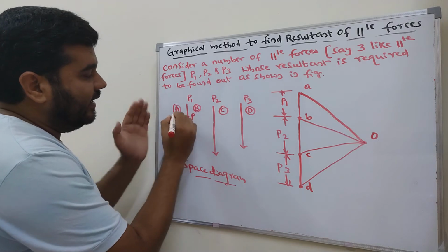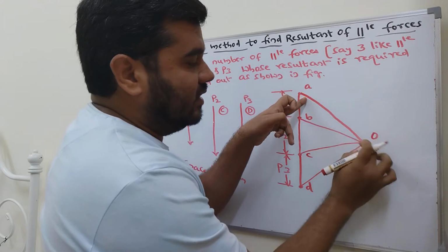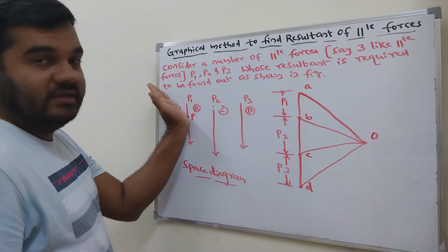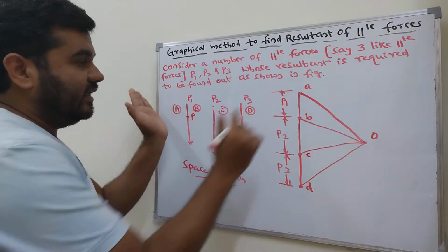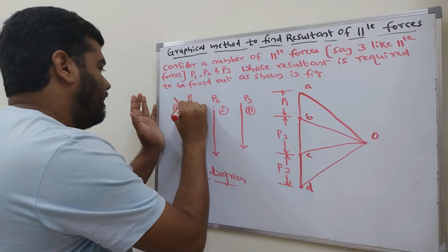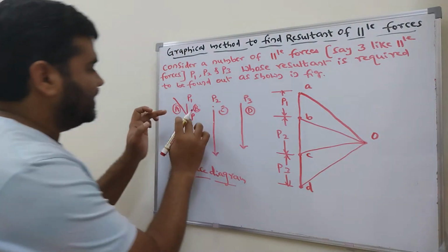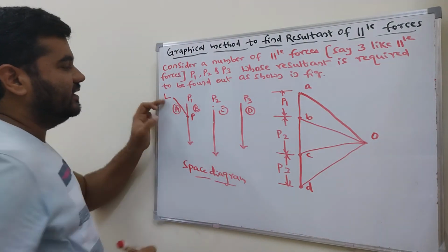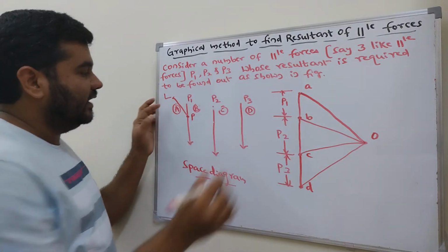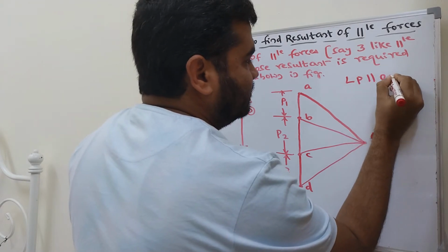Start with P. Draw a line parallel to OA. First start with this OA. Just this you need to transfer here from P, starting with P. That is, you need to draw a line parallel. This and this should be parallel. This I am marking as L here, this point. Here it does not matter, anywhere, but these two should be parallel. That is LP parallel to OA.